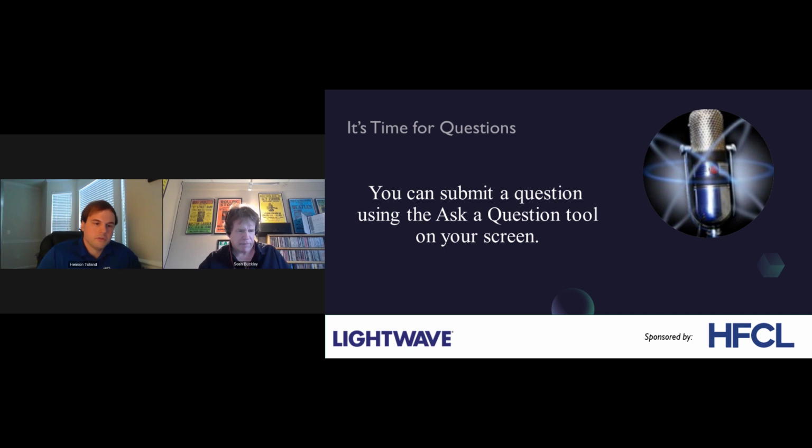Okay. Here's another question, and you might have answered this: does this type of cable exist for ADSS type installations? I think that's aerial. Yeah, that's aerial. So generally, you want to stick with large ADSS cables for that, but there are some smaller ADSS type cables that may fit the bill. Generally speaking, these should strictly be for a blown type application. But there are definitely smaller diameter ADSS cables that may fit exactly what the application is that's being asked here.